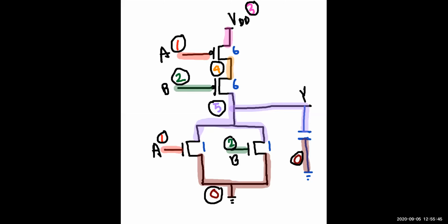Now we can start writing. So MPU again, copy, because this is PMOS, NMOS: MPA, MPB, MNA, MNB, right? Yes, sir. P type. Okay, now the sizing. At first, fix the sizing. This is 6, right? 6 means what? 24. Next one is also 6, it is also 24. Next one is 1 and 1, so 4, 4. Okay.